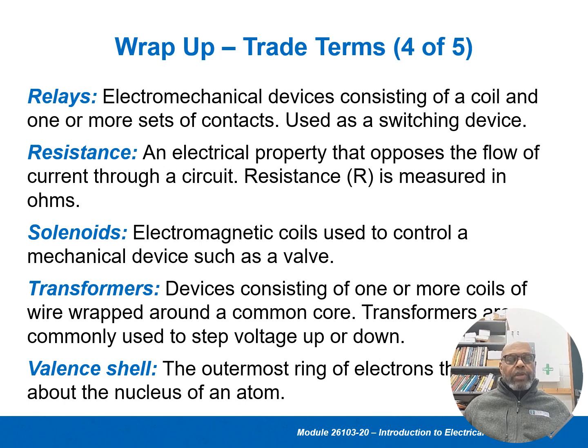So you can use electrical current, a magnetic field again, and a coil to pull a plunger to actually stop the flow of a fluid or something, and to allow it to flow through. So a relay will control an electrical circuit, turning it on and off, but a solenoid will turn some other flow on and off, like a fluid in hydraulics, or a water valve that's controlled electronically.